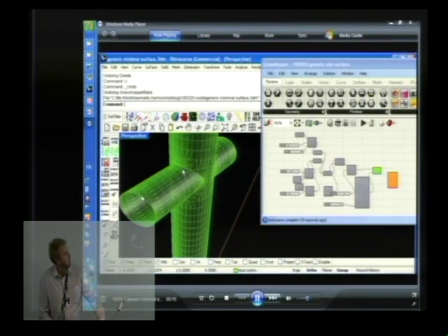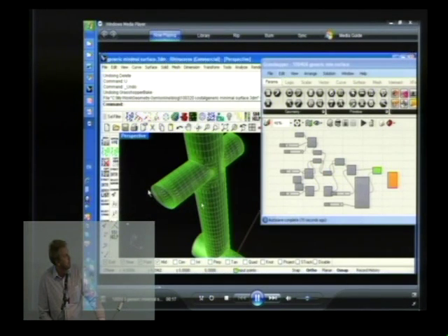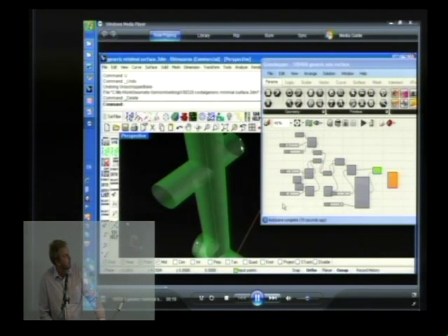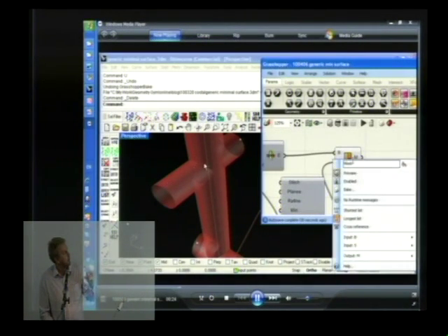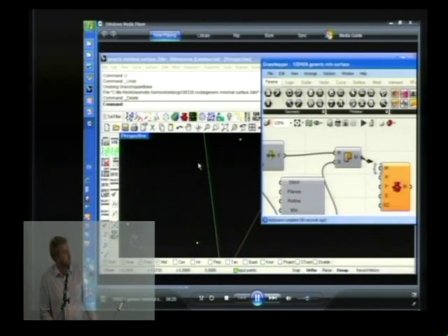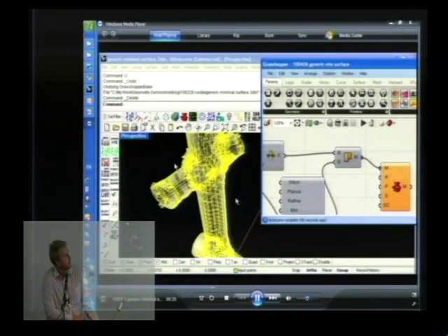It just requires a mesh, and any mesh node that exists on a free edge, so the boundaries of these cylinders, etc., will remain fixed. And any node on that mesh that's internal on that surface is free to move and shake itself into that smoothed or organic mesh relaxation. So visually, this component here is going to demonstrate and redraw the mesh at each particular calculation.